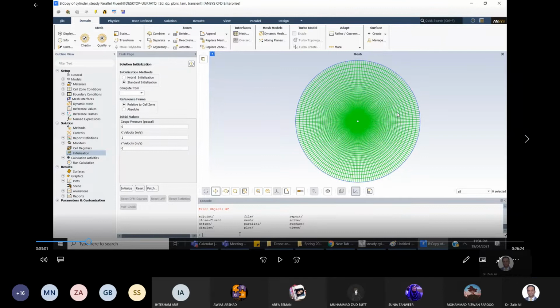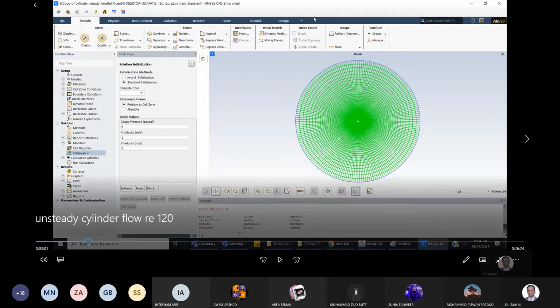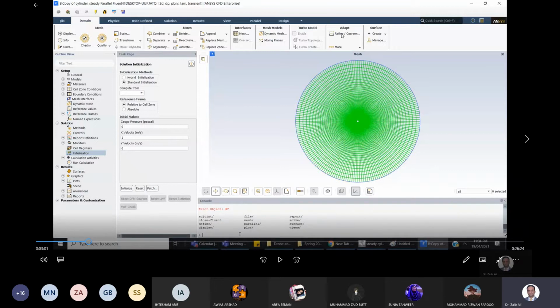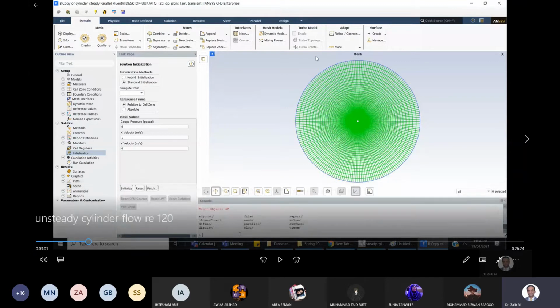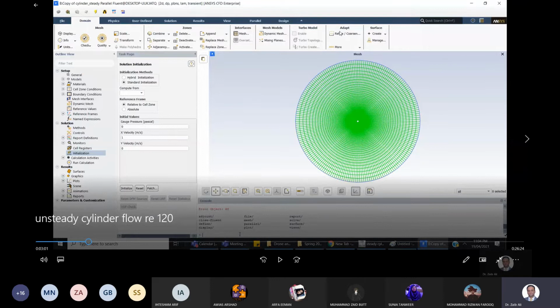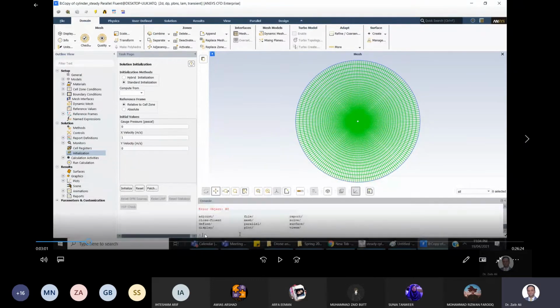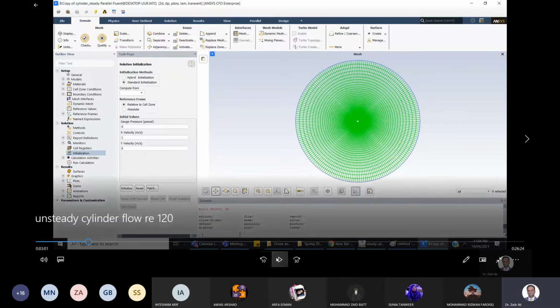So that is done normally by selecting this domain, and here we have this adapt menu. So in this newer version, they have hidden this region adaptation or patch, we say. So in the previous versions, there was this proper GUI for that. So in this newer version, how to change this menu? You go to this command line console and hit enter over here.